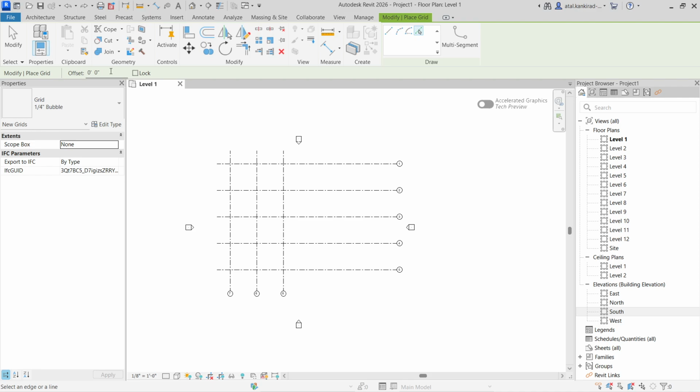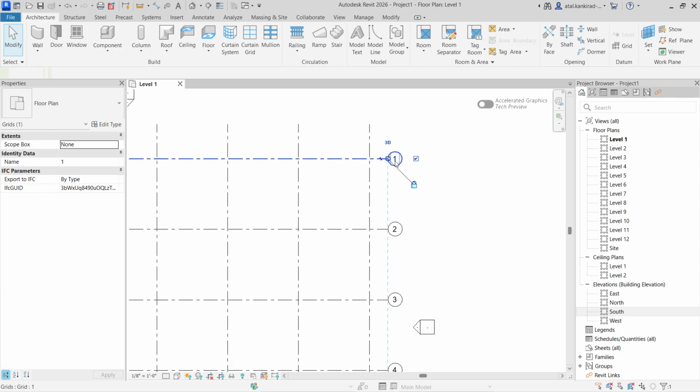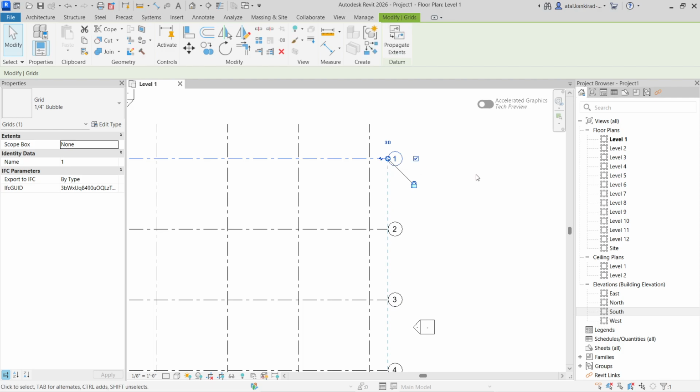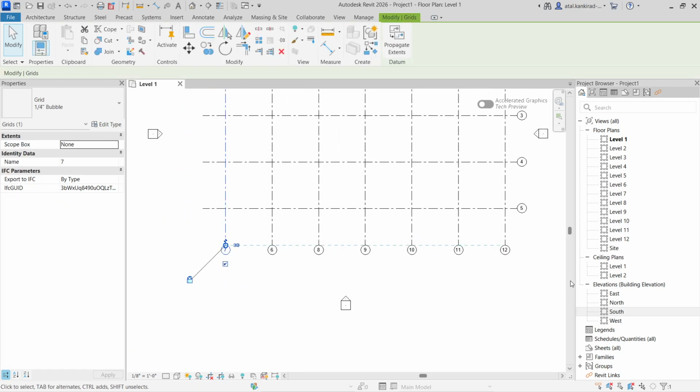And you can then again also just simply create them. So we'll just quickly finish this. Yeah, okay, this will be enough. In general, we can also rename this. If you want any 1, 2, 3, 4, I generally keep horizontal as 1, 2, 3, 4, 5, and have the vertical grids named ABCD.